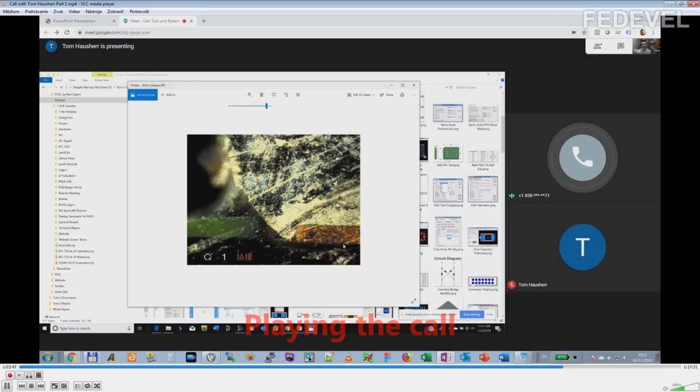And so when you get to a really small pin pitch for your BGAs, and you have to do a via in pad, we recommend that you grow the pad a little bit bigger so you don't collapse around it, okay? Because you have to put a via, a blind via or whatever kind of via, in the pad, because you can't fan it out like normal. And so you make your pad size as big as the ball, if not bigger than the ball. Then you solder mask define it.